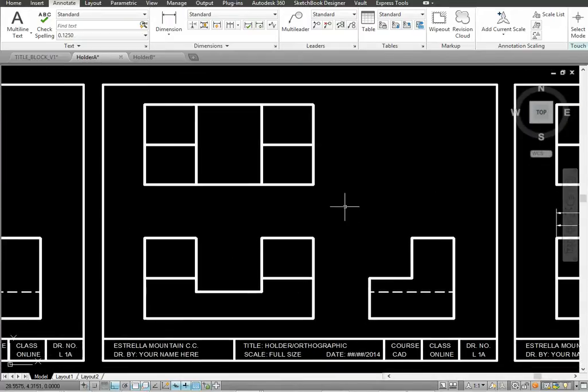It's as simple as this. You pick this command here, which is called linear. With object snap on, you grab endpoints, and then you pull the number where you want it to go. There will be other smaller dimensions added. If you place a dimension, you just could pick it and grab these grips, these are called grips, and move them up or down to whatever length you need. There are rules for that, but for now that's not important.